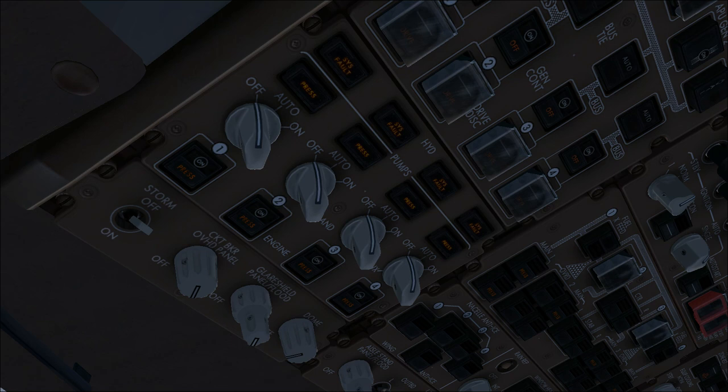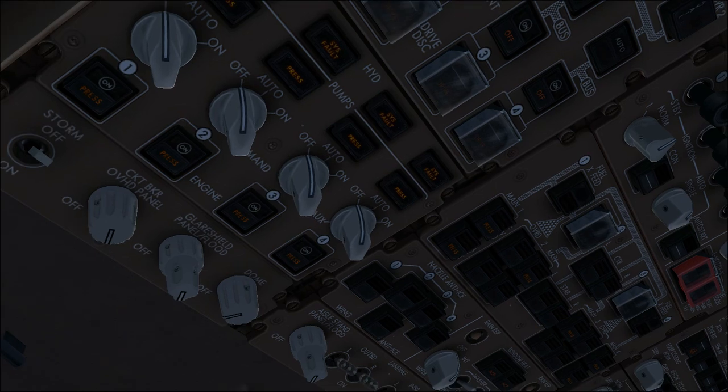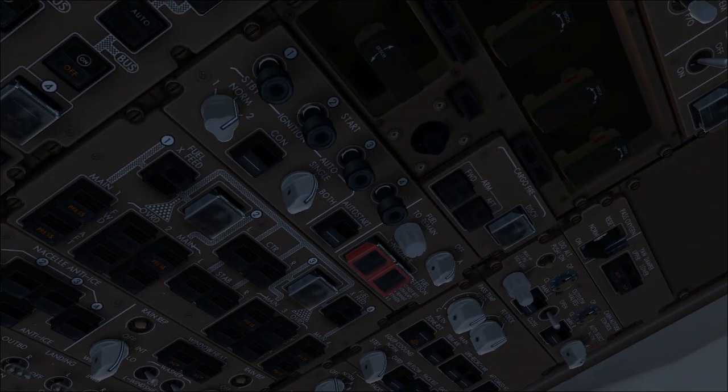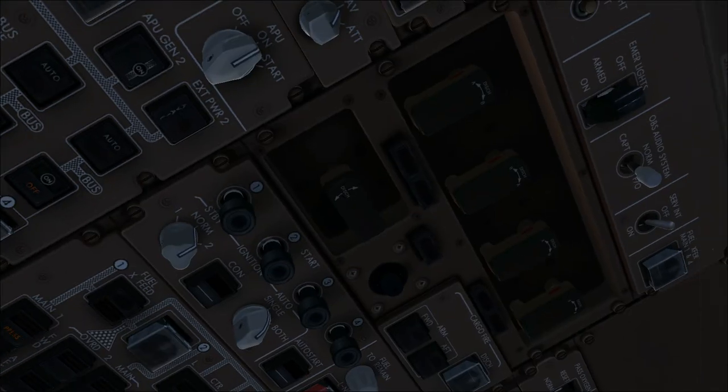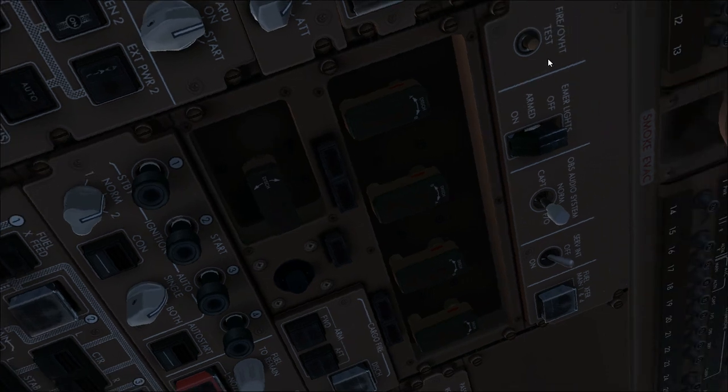Then we can move to the other column. Start up from here. We have the emergency light switch guard closed and in the armed position, that's fine. Observe the system is normal, service interphone is off, and fuel transfer main info is off, as you can see, so it's fine. We should do the fire override testing. I just forgot about it, because you should do this before starting up the APU, and after the electrical power up checklist. Anyway, I will show you now.